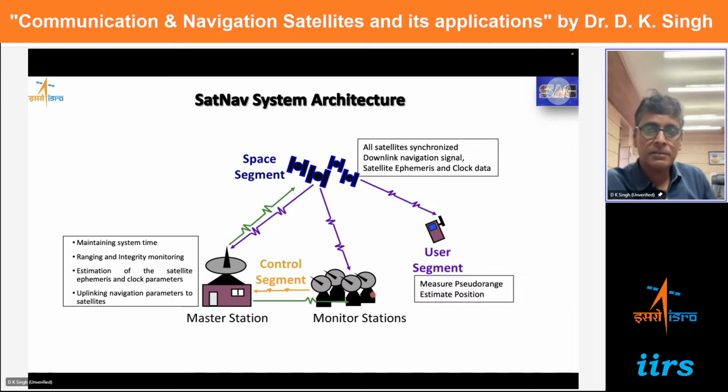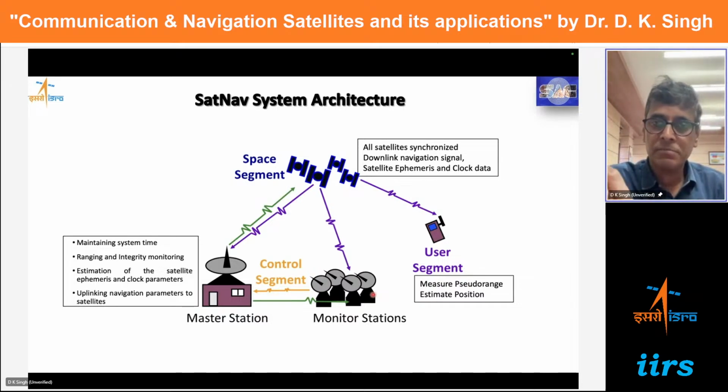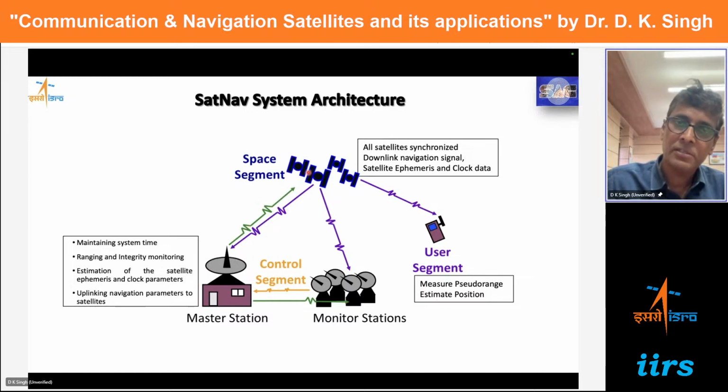So in the satellite navigation system, we are using lower frequency. So there are various impairments which affect the accuracy. So we have to do a lot of monitoring, mathematical modeling of everything and transfer everything to the master control station, and the control station will uplink all these parameters, and those parameters will be embedded in the signal which we have seen previously to the user receiver. And the user receiver will use all that information to apply appropriate corrections in the computed information.